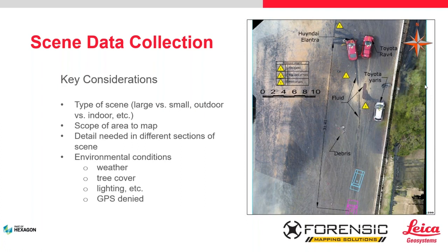It's going to take a series of photographs in a flight application, and then those photographs are going to be stitched together in Pix4D, and it's going to give you what's called an orthomosaic of your scene. So now you're going to capture a large area. That orthomosaic will be to scale and perfectly 90 degrees to the ground.